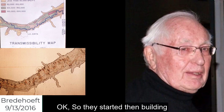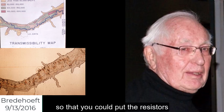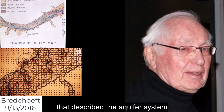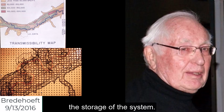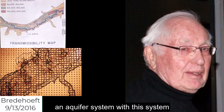Okay, so they started then building resistor capacitor networks on a pegboard so that you could put the resistors on the pegboard and build this network out that described the aquifer system, and at each node, you could add a capacitor that would represent the storage of the system. So by doing that, you could describe an aquifer system with this system of resistors and capacitors.